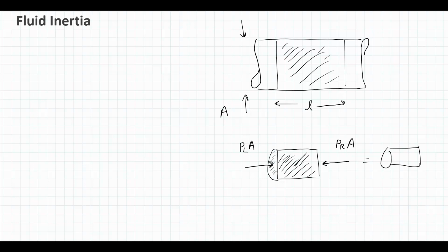So let's establish some coordinate system here as it's developing into a free body diagram. So if x is going to the right, then the inertia is going to be the mass of the fluid times its acceleration. So the left-hand side are, again, the forces acting on this little isolated cylinder or prismatic solid of our fluid, and the right is its inertia, its mass times its acceleration.